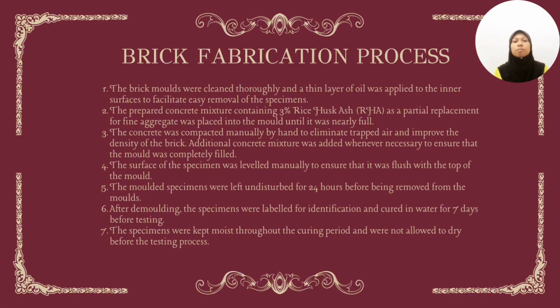The molded specimens were left undisturbed for 24 hours before being removed from the mold. After demolding, the specimens were labeled for identification and cured in water for 7 days before testing. The specimens were kept moist throughout the curing period and were not allowed to dry before the testing process.